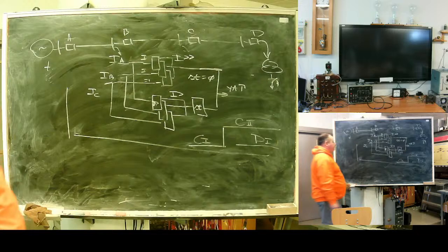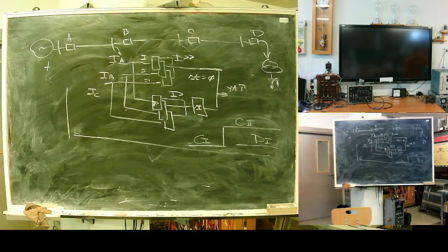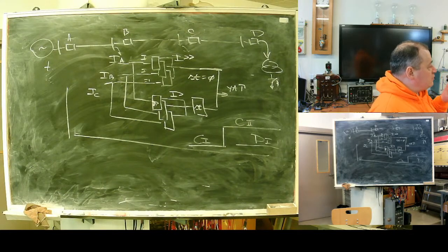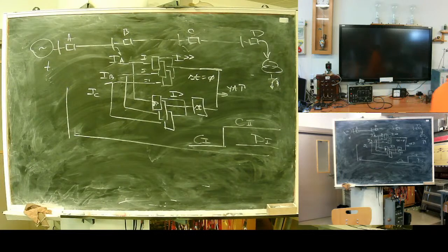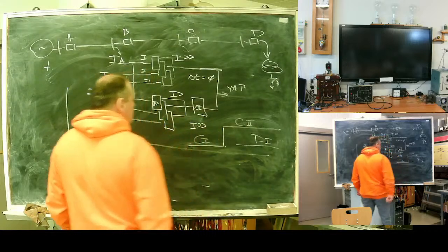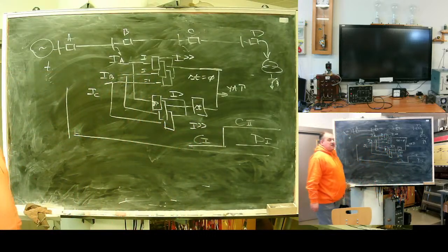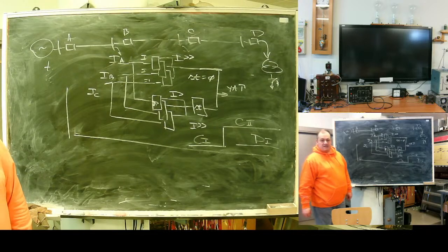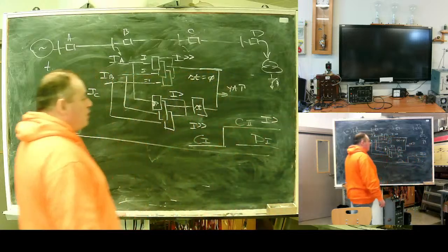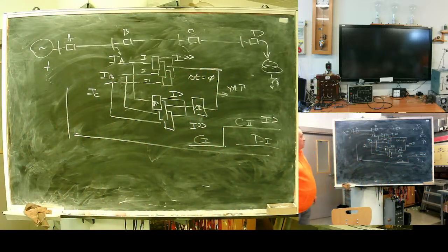Current grade. The idea is to have two sets of overcurrent function. One instant, one delayed. Instant will operate with delay 0. This one is delayed. Why am I showing these two marks?